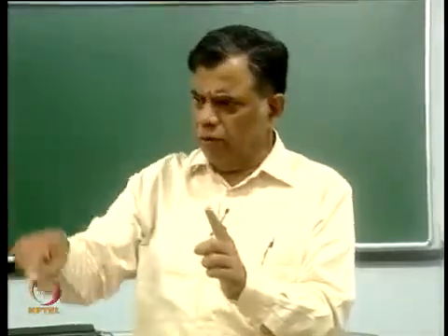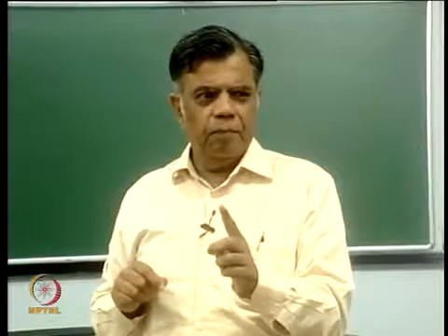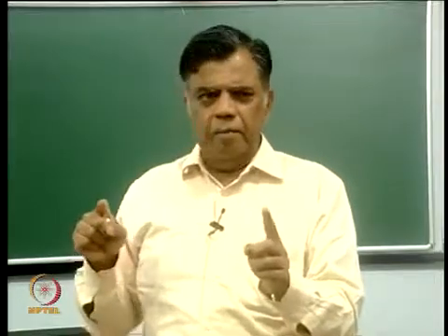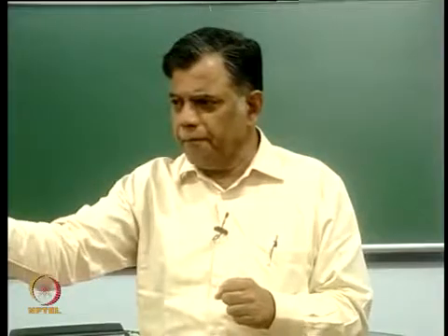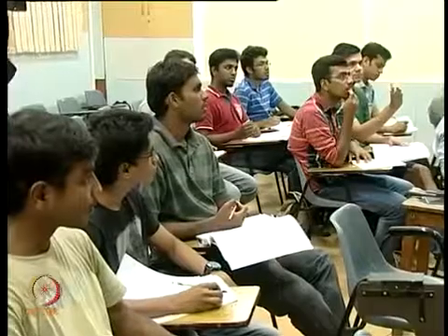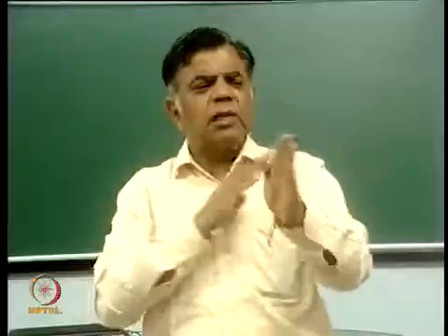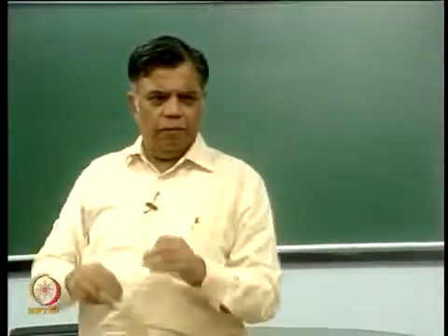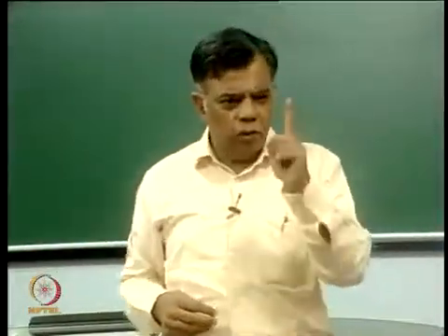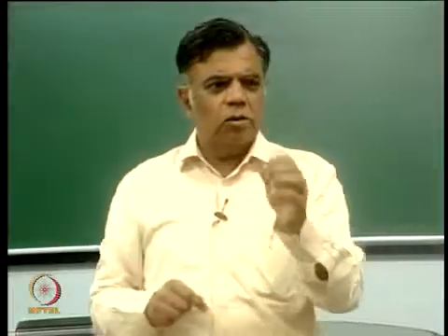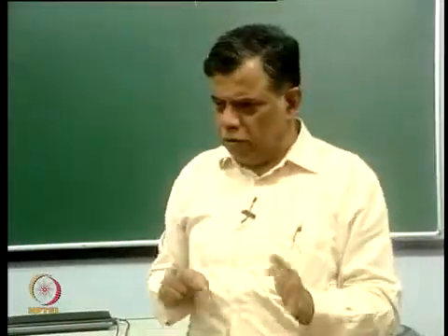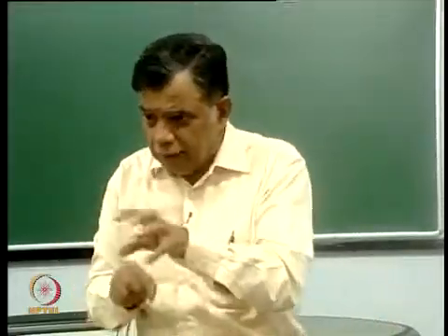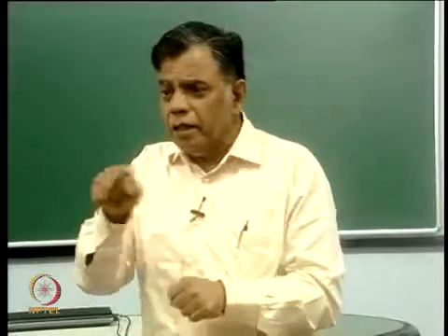Laminar itself, what all you have done? Fourier's law? At the surface, no, this is what I wanted. At the surface, you apply the Fourier's law, write down. So, Fourier's law comes into picture. Minus k dT by dy at y equal to 0 equal to, isn't it? That is how we are going to get it.